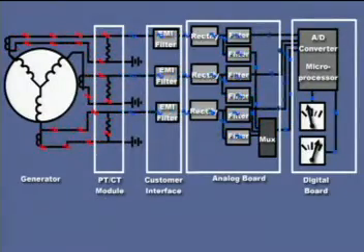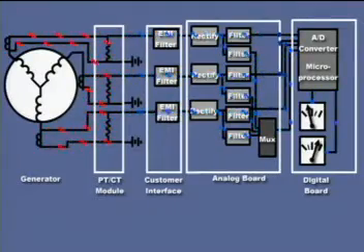When the digital board receives these signals, it uses the heavily filtered signal from the multiplexer, MUX, for display and power calculations. The lightly filtered signal is used for short circuit regulation.